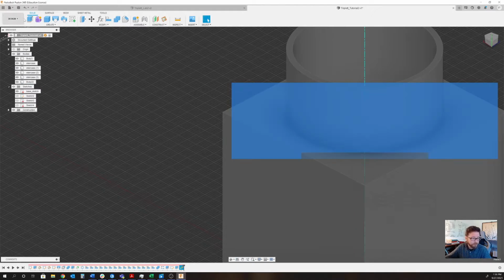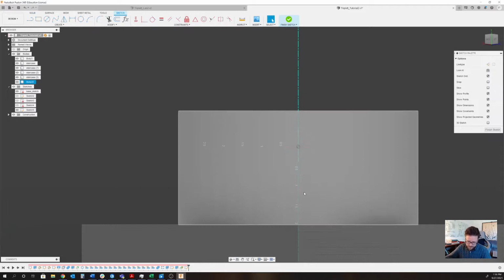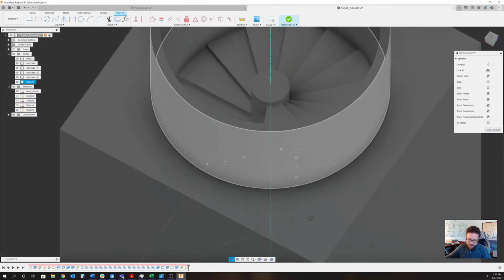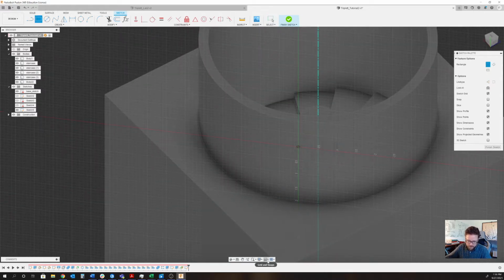I'm going to select that and create a new sketch here. And I can also maybe change my view a little bit just so I can see what I'm doing. I'm going to grab a 2-point rectangle. I'm going to turn my snap to grid back on. And I'll make this 1 meter wide by 1.6 high. Just a simple rectangle for the moment.